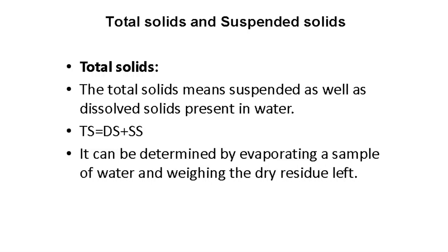Total solids and suspended solids. Total solids means the suspended as well as dissolved solids present in water. So TS, total solids, are dissolved solids plus suspended solids. It can be determined by evaporating a sample of water and weighing the dry residue left.